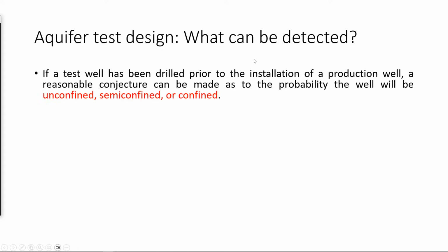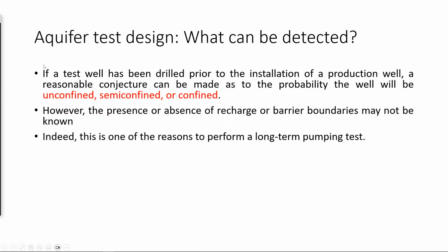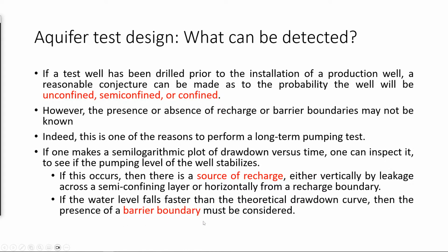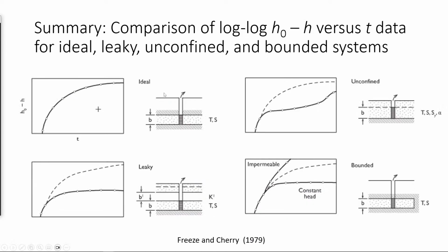We already talked about this, what can be detected, whether this is an unconfined, semi-confined or a confined aquifer. What can also be detected is if there is a recharge or a barrier boundary, and we talked about this. Again, this is just a review of what we did. Here, remember we talked about this. This would be the ideal case, that would be the unconfined case, that would be the leaky case, and that would be the impermeable and constant head. All this could be detected from a carefully designed pumping test.